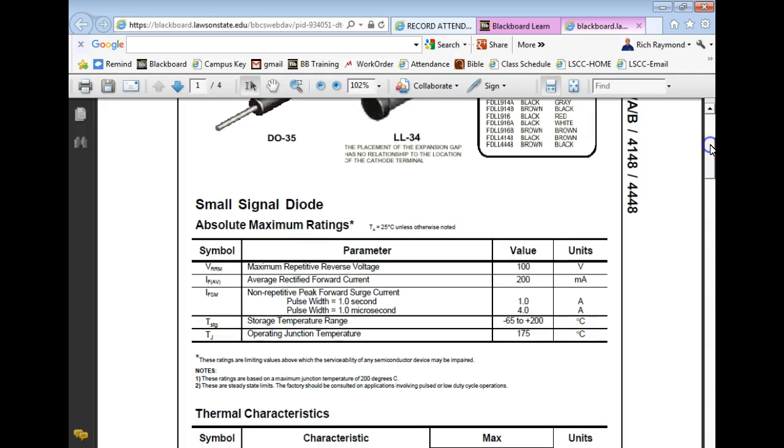Now what we start off with, number one, in semiconductor data sheets, the first table we see is something called the absolute maximum rating. Now what the absolute maximum ratings are, they do not guarantee operation. They guarantee the device will not be damaged. There's a big difference, right? See how the device operates. So this is where the breakover voltage is going to be.